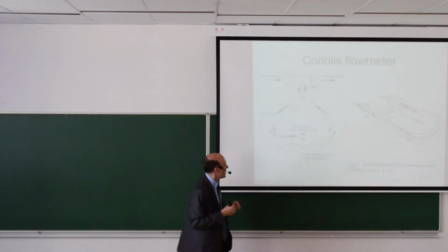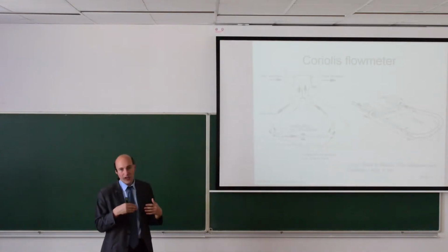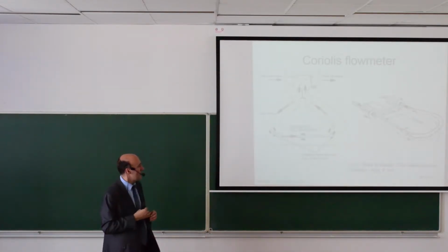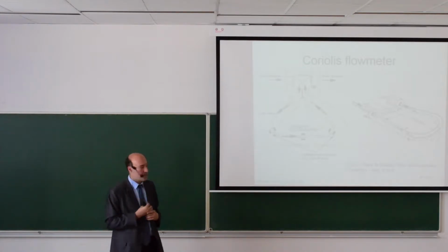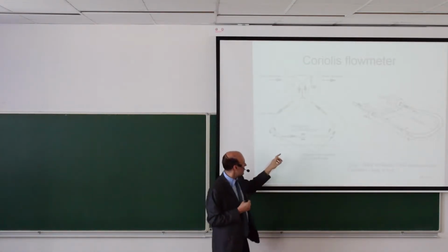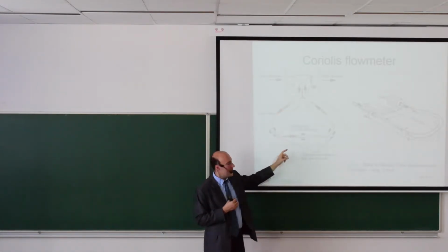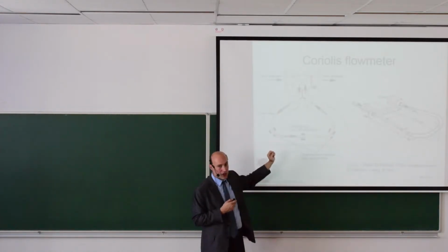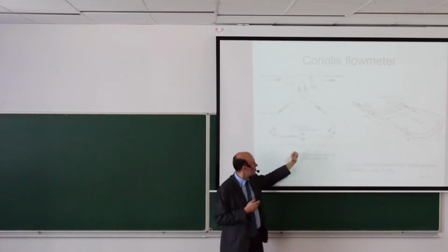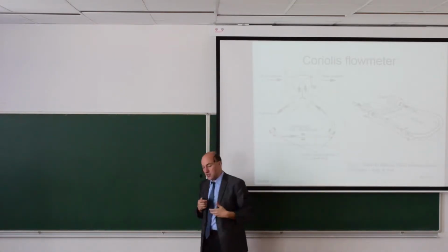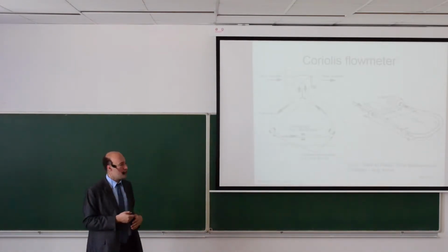So when you look at the signals from those sensors, it will be some form of sinusoidal signal, but there will be no phase shift. Once you apply flow, the movement will continue, but there will be a phase shift between this position and this position, and this phase shift will be proportional to flow.